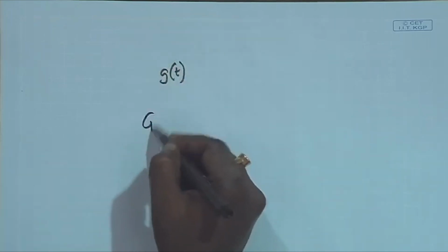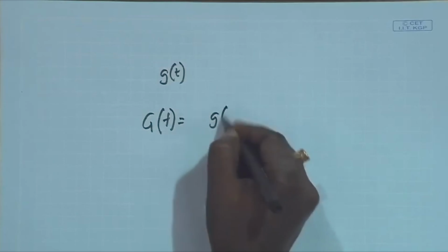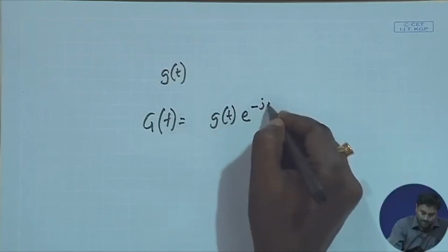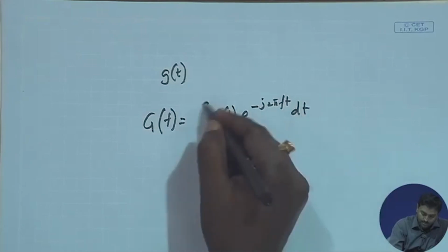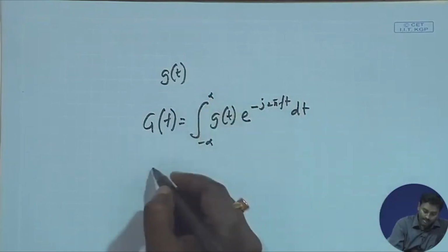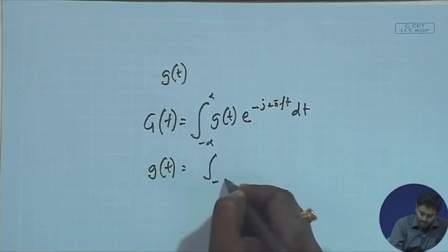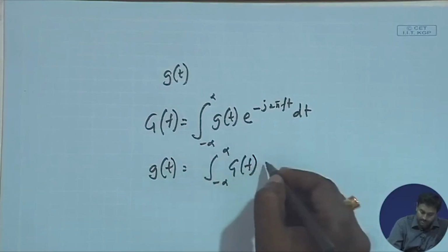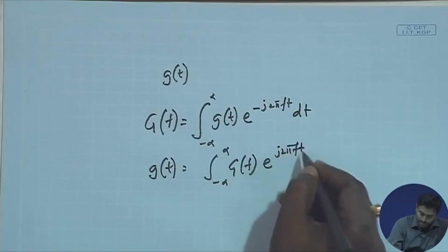Okay. So, whatever it is, now what we have done is we have understood what is Fourier series and what is Fourier transform, how we get Fourier transform out of Fourier series and what is its significance. So, for any signal GT, we have also got these two relationships, that one is this GF which is Fourier transform, it is GT e to the power minus j 2 pi ft dt integration minus infinity to plus infinity, and we get inverse Fourier transform which is minus infinity to plus infinity GF e to the power plus j 2 pi ft df.